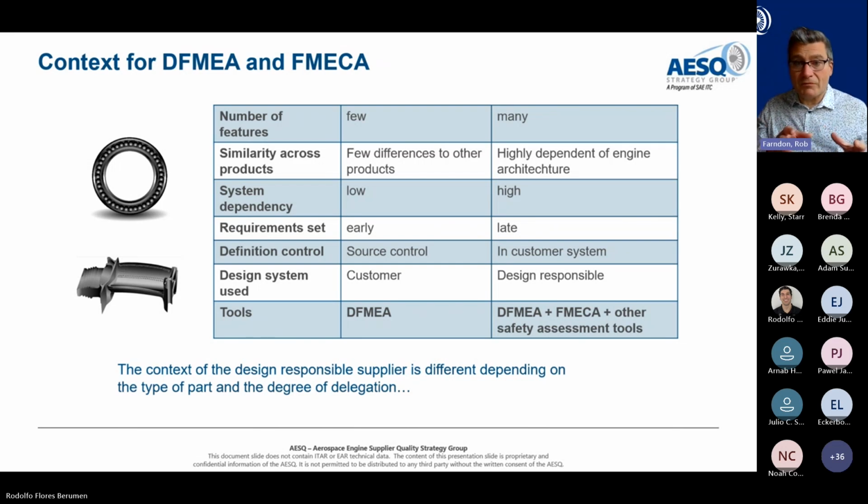Those failure mechanisms and their propagations up to the platform level are highly dependent upon engine architecture. For that reason, FMECA tends to go with the design responsible organization. We talk a lot about the customer system here because that is what really determines the impact of an individual component failure.